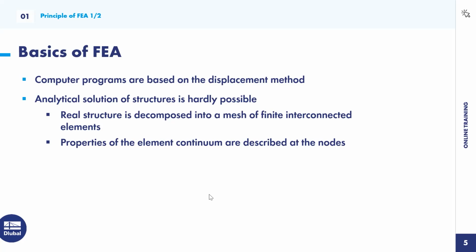We will have on the one hand connections between two finite elements, and within these connections we have linked degrees of freedom. I mean, you can imagine a plate connected to another plate, and at their intersection, let's say, the deformation in the z direction, so in the vertical direction, must be the same.